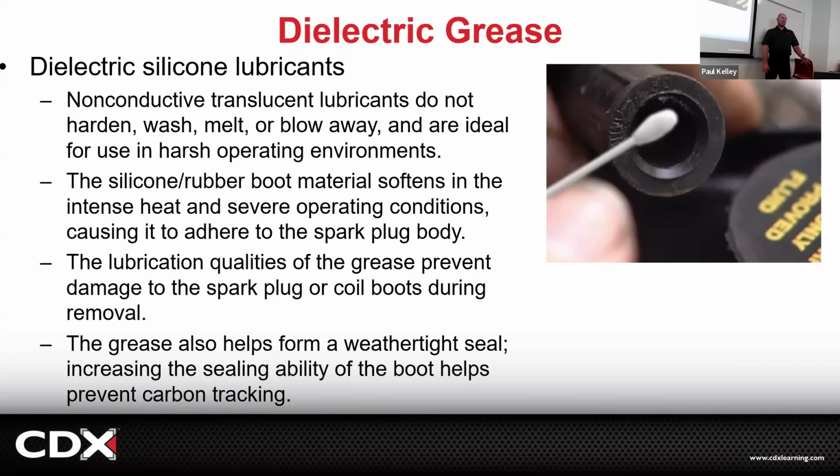But this is the thing though. The secondary ignition has plenty high enough voltage. If we put just a little bit of dielectric grease in here with a Q-tip or non-generic cotton swab, that's going to help this boot slide onto the spark plug or onto the cap or whatever. And then the metal to metal is going to scrape the dielectric grease and have a nice connection. But that dielectric grease also functions as like a waterproofer, right?